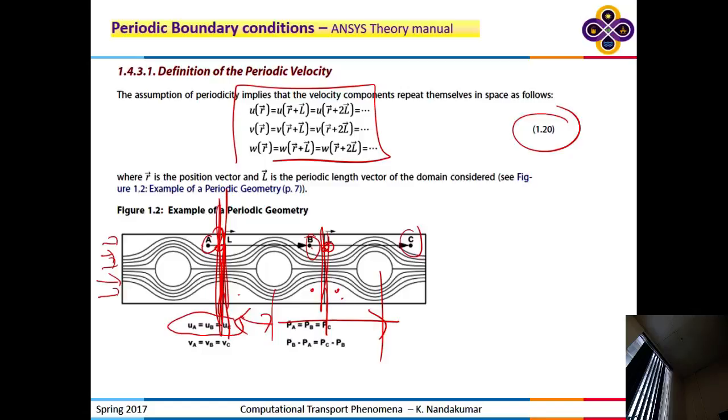I don't think so, because the inlet will have a certain impact on the flow as it evolves. So this concept of a developing length becomes important here. It needs a certain length for the flow to become fully developed, and then it can repeat itself. If you don't have any obstruction, it takes a certain length, it develops into a fully developed state, and the velocity profile doesn't change. But if you have obstructions after it has developed to that length, it will obey the obstructions. So it will be periodic after that.